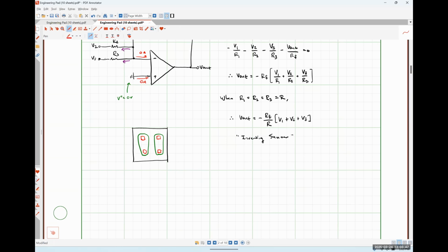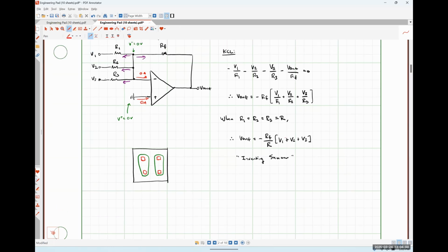So the load cell itself, if you look at the data sheet, it's going to tell you it might generate 1 millivolt for every kilogram or something like that. And we could use the ratio of resistances to convert that output of the load cell from millivolts per kilogram into essentially volts per pound or something like that by scaling it in that way.